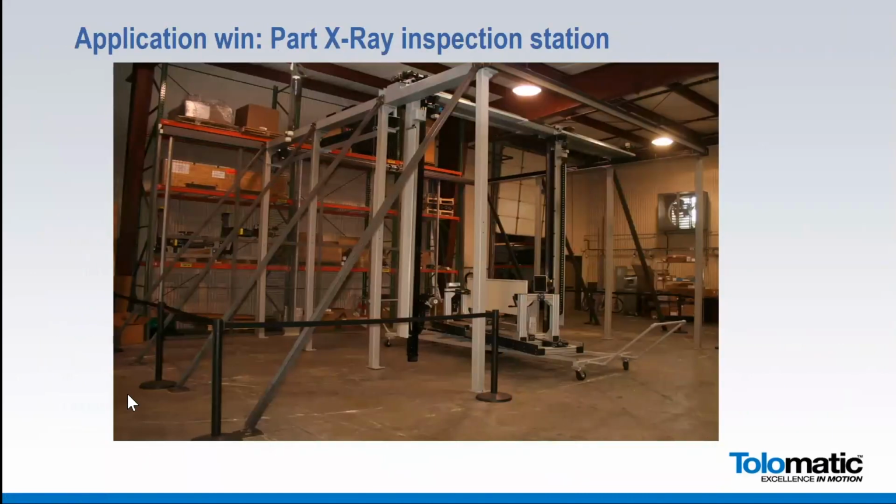And here's a large design system here. You've got a couple axes of motion, and this was doing inspection of, I believe, airplane wings, so X-ray inspection. Luke, I don't know if you want to add any more color commentary on that. Yeah, no, that's pretty much what you just said. It's an airplane wing inspection system, X-ray inspection system. So you would have an X-ray generator and an X-ray detector moving in sync with each other and facing each other, looking at this wing at various angles. So that's actually a 7-axis system, 5-axis in the gantry and 2-axis in the wing holder.